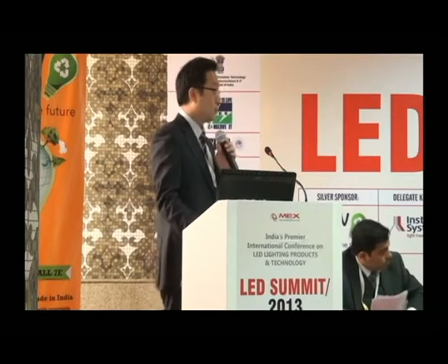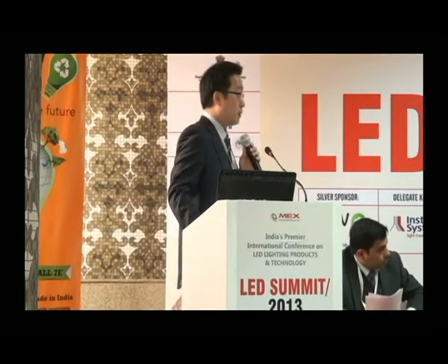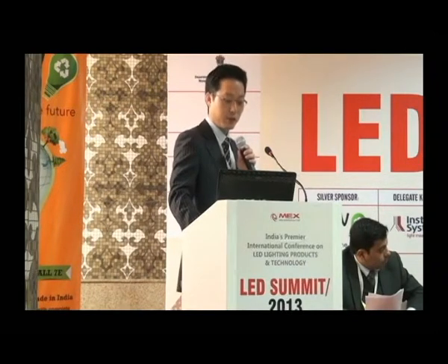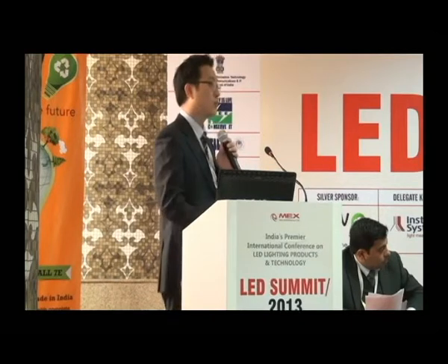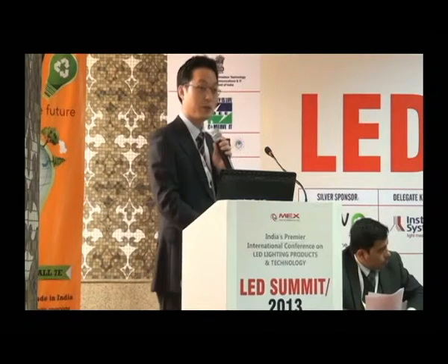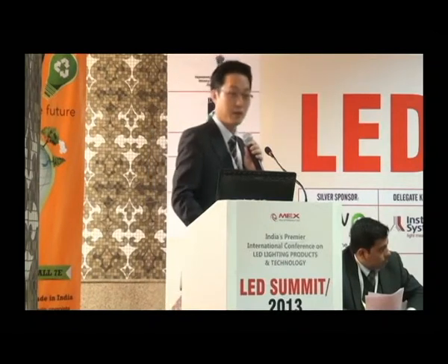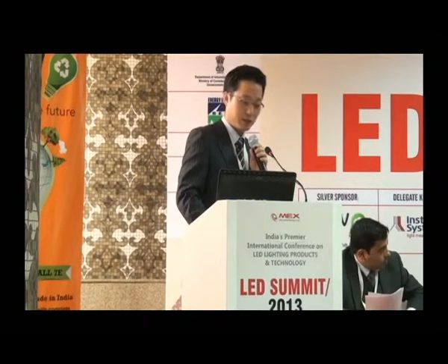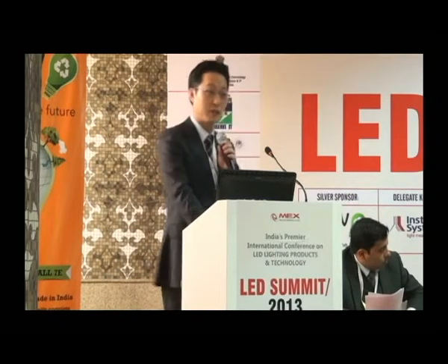Now there is no argument about why silicone is the best material for LED lighting applications. As you know, epoxy used to be the main material for encapsulating LEDs. But the problem with epoxy is that it is very weak against thermal aging.